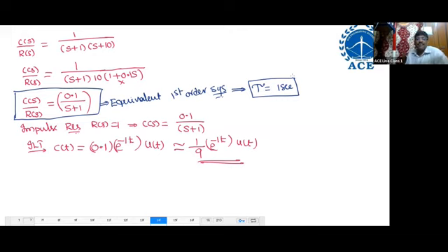But no need to do it like this. Simply identify the insignificant pole, bring it into time constant form and neglect it, and then write. Then it will become the equivalent lower order system. Why? Because you should neglect an insignificant pole only in the time constant form, because the system gain should not change.